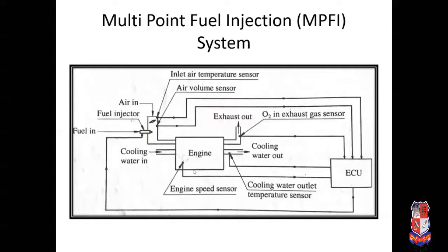So the different sensors send the signal to the ECU, and the ECU will actuate the solenoid operated fuel injector. So according to the different sensors, according to the condition at the different points, right? The fuel is injected to the cylinder.